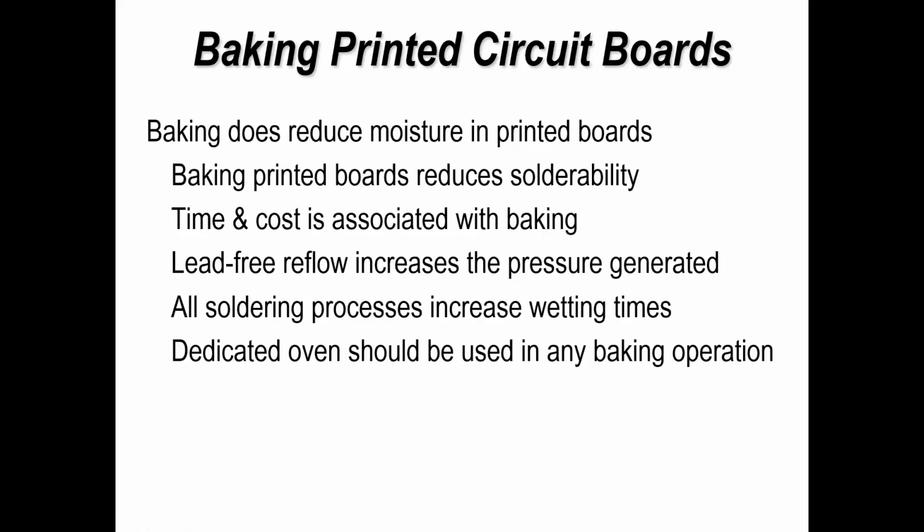So back to the boards, bake, yes. It reduces moisture present in the printed circuit board. It reduces solderability, so you've got to be careful. Time and cost is associated with baking. So that's one of the reasons why I say that if you've got a moisture sensitive part, you've got to weigh out the time, temperature, and the impact of your baking process. But you don't want to bake unnecessarily. So if your product A had a problem some years back, you really want to find out if the problem's gone away and whether you're baking and wasting time and energy for no value because the problem isn't there anymore.